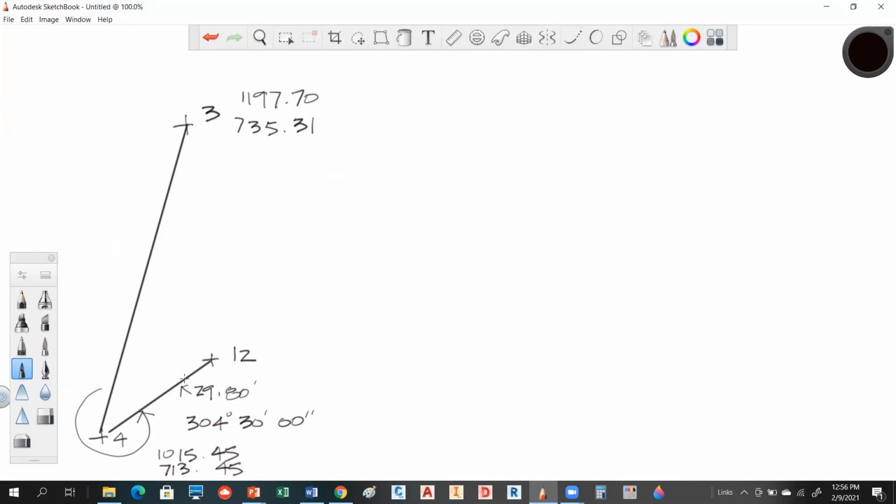Now, this is the azimuth which we're after, the azimuth we need. Since this is going counterclockwise, that would be a subtraction. What else could you do if you didn't want to mess with the subtraction? What could you do to make that simpler? Find the internal angle. Yeah. So instead of using this guy, we could just solve that, subtract from 360. Yeah. And I think that would probably be easier. So that's what I'm going to do. Instead of messing with all that negative, I'm just going to go with that one.